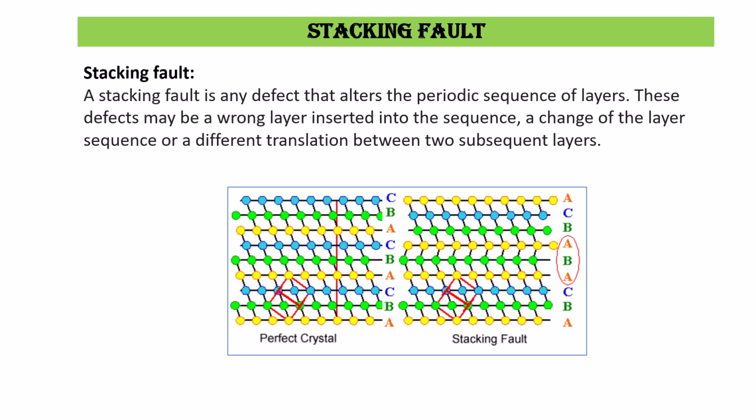Stacking fault. A stacking fault is any defect that alters the periodic sequence of layers. These defects may be a wrong layer inserted into the sequence, a change of the layer sequence, or a different translation between two subsequent layers.